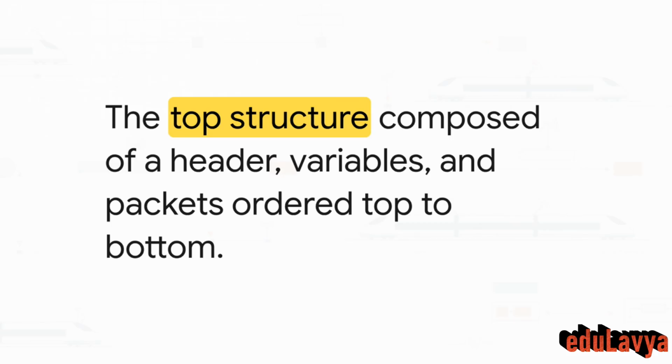Finally, all these packets and individual variables get assembled from top to bottom into complete messages, also known as telegrams. This is the top-level data structure. Much like a highly formalized sentence, it contains a message header, plus a predefined set of variables and packets. A perfect example of a message would be an SR authorization or a full movement authority. These messages provide the overarching command and control logic, feeding the onboard computer everything it needs to generate a safe braking curve and monitor the entire journey.